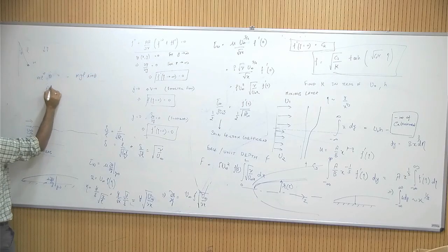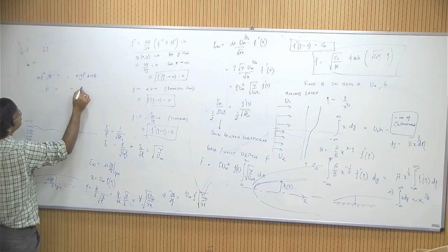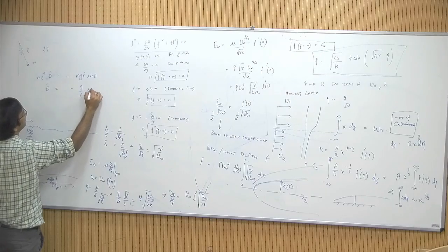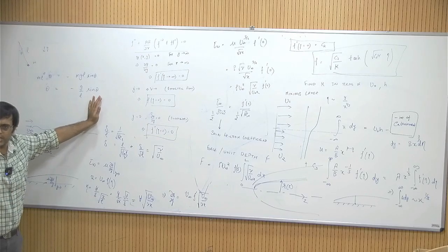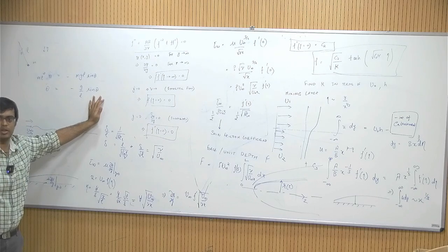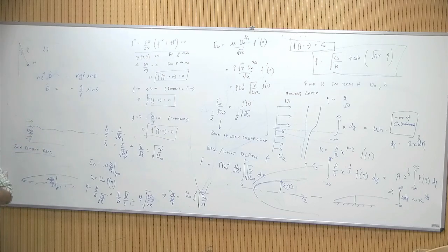Okay, so theta double dot equals minus g by L sin theta. Is this a linear equation or non-linear equation? Non-linear. Why? Because of sin theta. Okay, if we did an expansion for very small thetas, we will get theta minus theta cube by 3 and so on and so forth, and there are non-linear terms there.